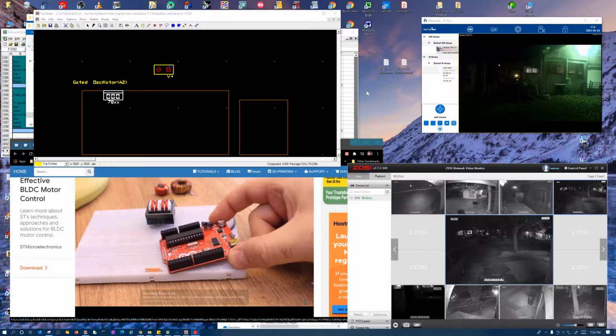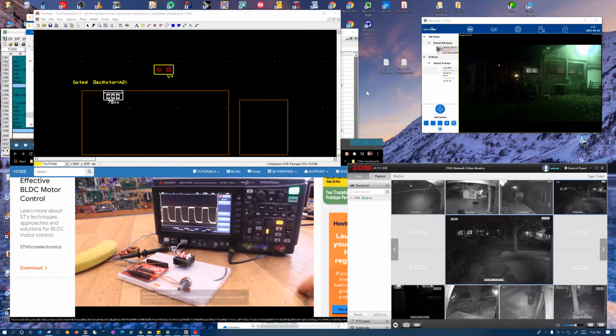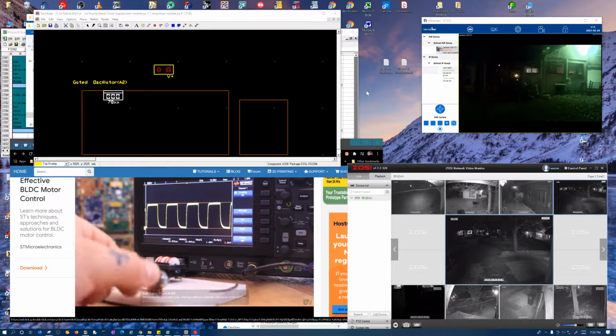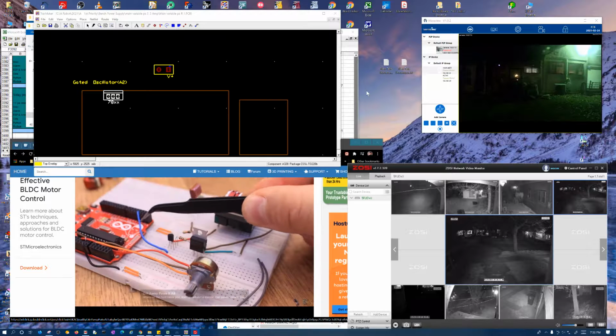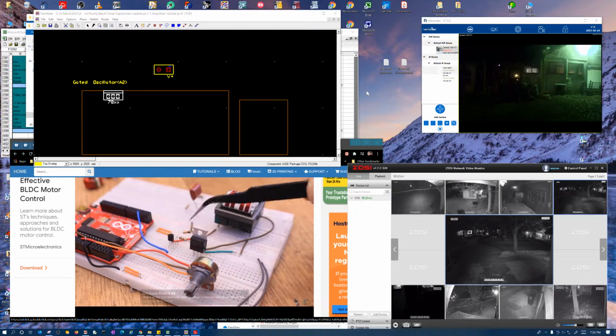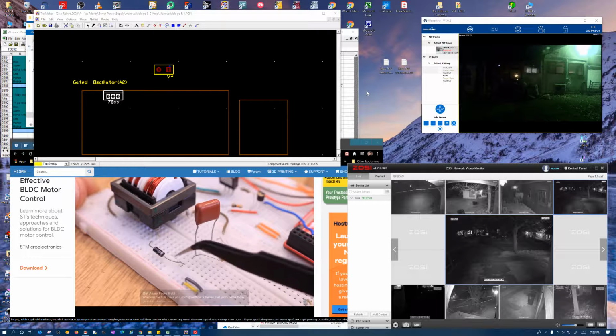I will use the Arduino to create a fast PWM pulse that will change its value according to this potentiometer, as you can see now on the oscilloscope. We will see later how this pulse can change the output voltage of our circuit. I apply this pulse to some transistors that will be connected to the primary winding of the flyback transformer. And at the secondary we have to place a diode, a capacitor, and a small resistor as a load.